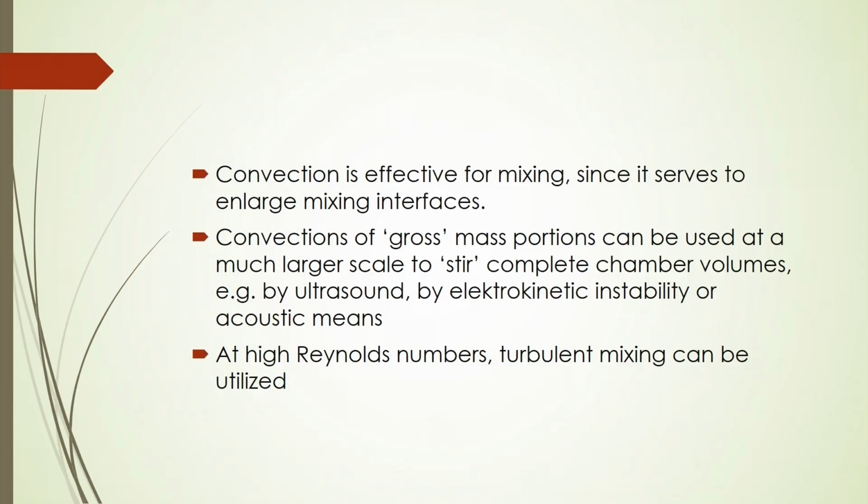Some other means, like ultrasound, or some other electric field, also can be applied to get micro mixing. At high Reynolds number, you can have turbulent mixing that can also be utilized just by making a mechanical provision to the channel, so that you can get high turbulence at high Reynolds number, and intermixing will be more there.